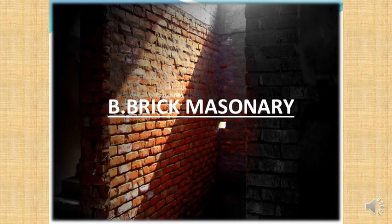So having said that, we'll go on to brick masonry, but one other thing, I do want to talk about a couple of disadvantages with cavity walls. The main one being that if you're building a thicker wall or building two walls, it's going to add a lot of expense, isn't it? And the other big disadvantage is it's going to reduce the overall size of the rooms in the house if the walls are thicker, because they're making room for these cavities.